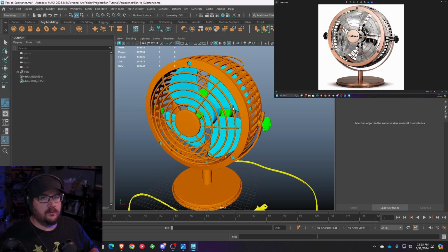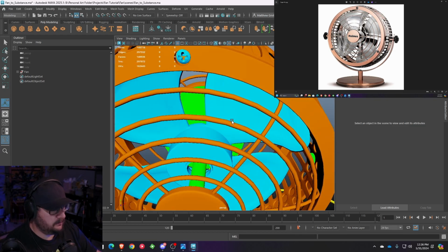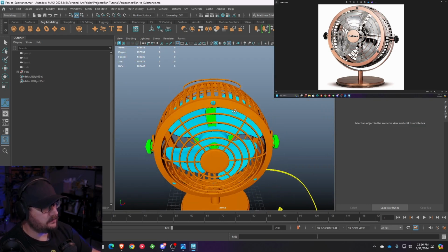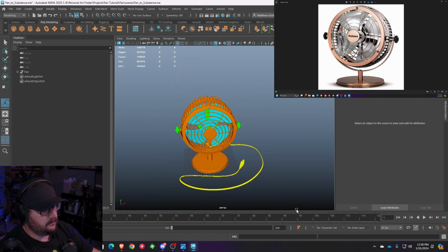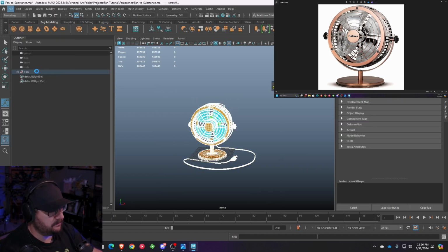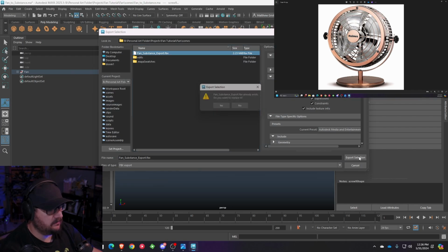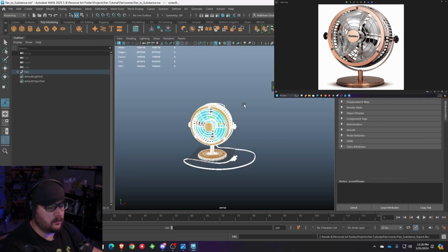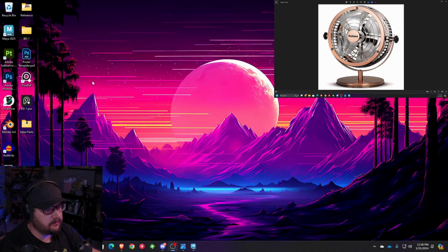You still can do the low polygon model. That's totally fine. You can also import the high polygon textures onto the low polygon model because they're going to be in the same UV island locations. However, this is the way going forward that I'm going to work with this. So with that said, select everything again, File, we'll go to export one more time, and we're going to do the same export depending on what you're working with. I tend to work with the high polygon models in Substance just because I like to look at them and see what I'm dealing with.